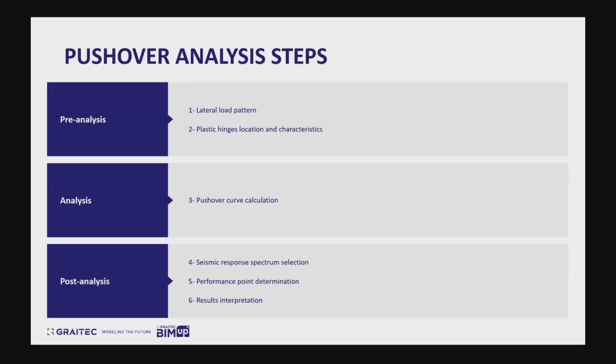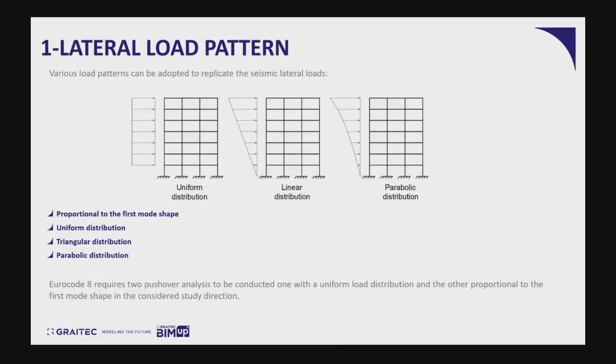Here we need to define first the lateral load pattern to apply on the structure, and second, the plastic hinges' location and characteristics. As we said, during pushover analysis, seismic loads are represented by a horizontal load pattern that is increased monotonically on the structure. This load pattern is defined by seismic codes.